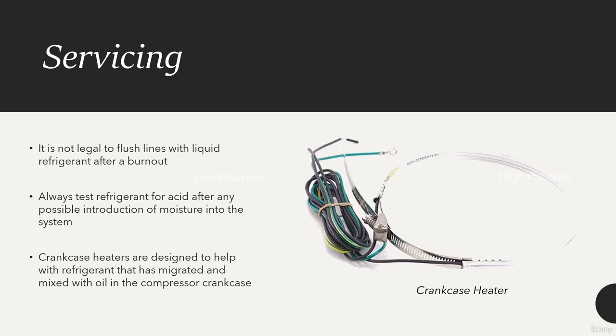Crankcase heaters are designed to help with refrigerant that's migrated and mixed with oil in the compressor crankcase. It's also used to help cut down on the possibility of oil foaming.